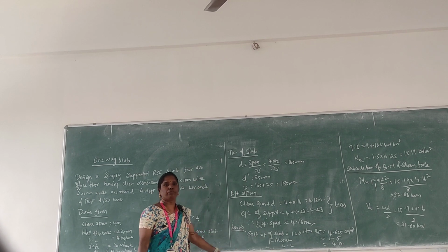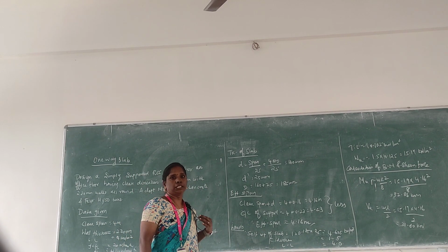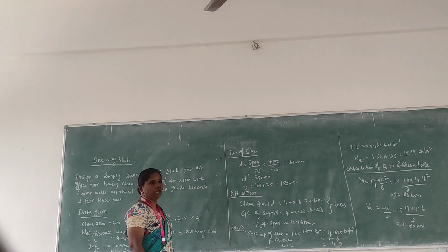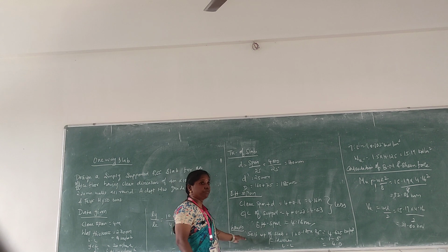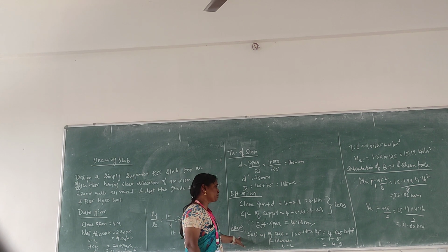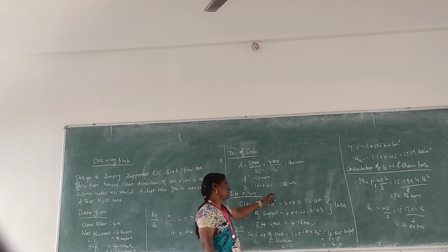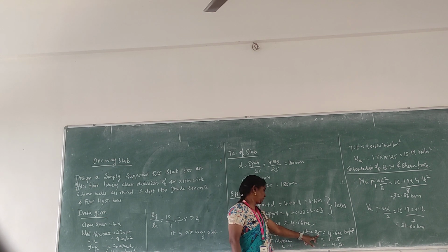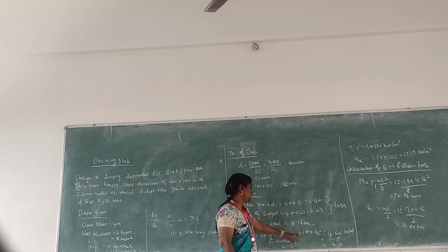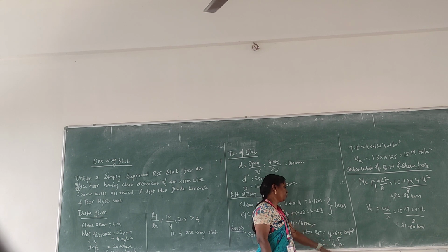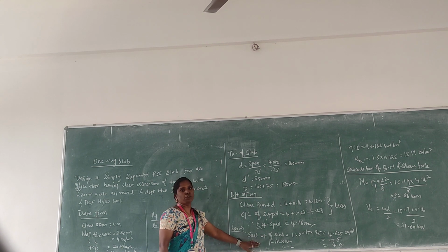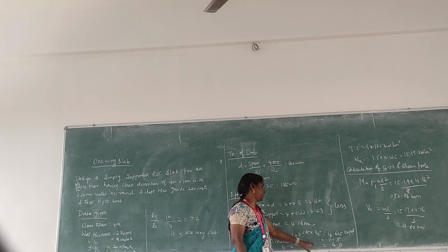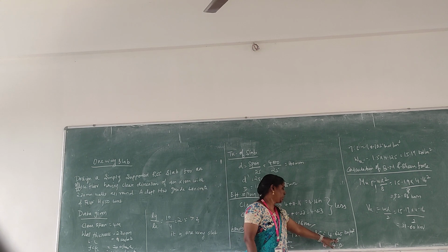Next step we are going for loading. There are two kinds of loading in the slabs, one is live load and the other one is dead load. For dead load we have to calculate the self weight of the slab. The overall depth of the slab is 185 mm, therefore depth into unit weight of concrete is nothing but self weight of the slab. So, here it comes to 4.625 kilonewton per meter square. Next we go for finishes. In the dead load, finishes come. So, finishes we are taking as 1.5, it is an assumed value.